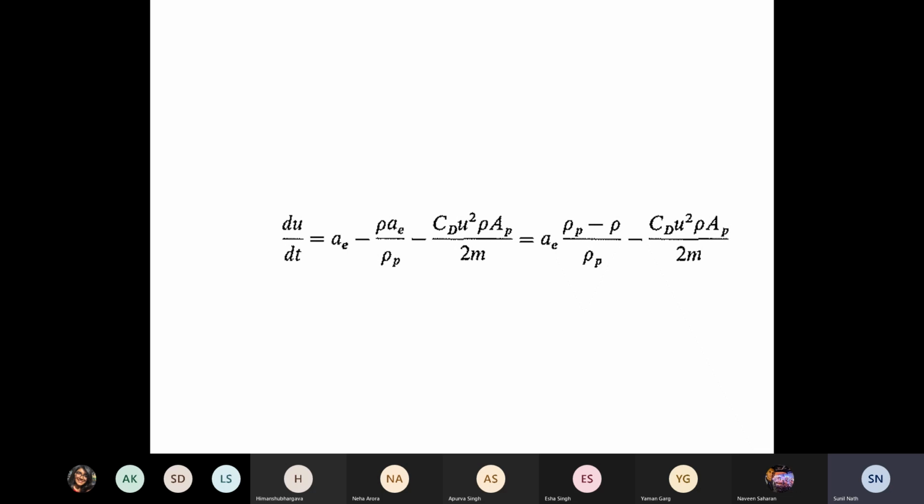So what I would now want you to do, which is, as I said, a very good approximation for free settling under gravitational conditions, is to knock off that mass times acceleration term as given in the slide and obtain the general equation for the maximal velocity. I call it the general equation because nowhere have you said it's a sphere or a cylinder.